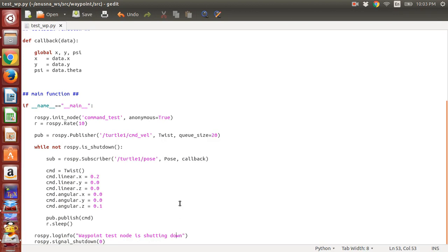One is where you check the absolute difference between the current x position and the x coordinate of the waypoint, and the current y position and the y coordinate of the waypoint, and make sure that they are within 10 or 15 or maximum 20 centimeters. And the other way to do that is you can use a range. You can say if the range between them is 5 centimeters or 10 centimeters at max, then the vehicle can stop there.